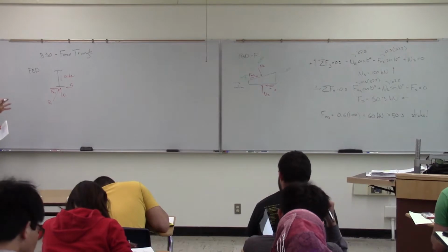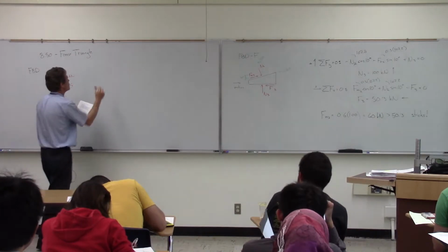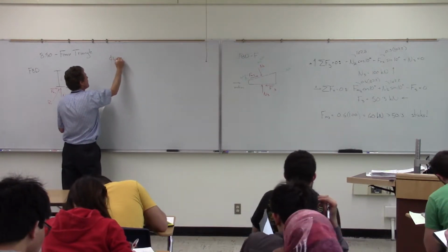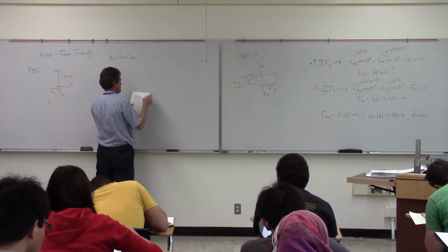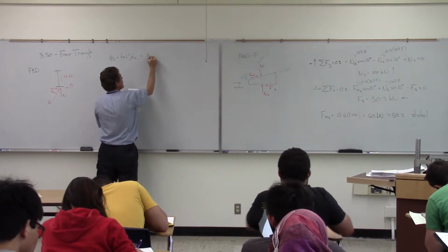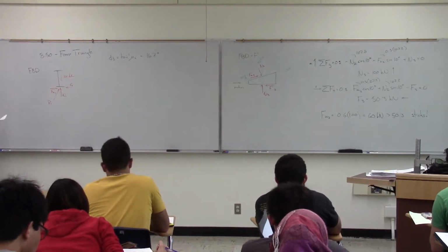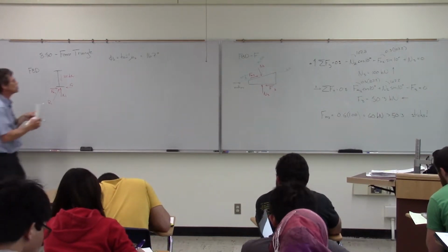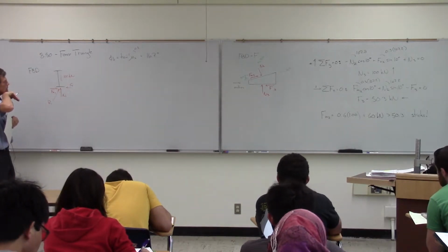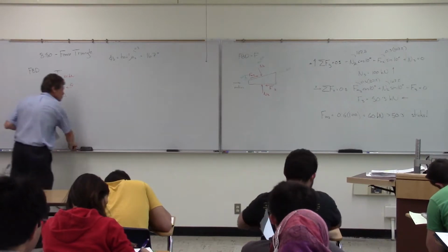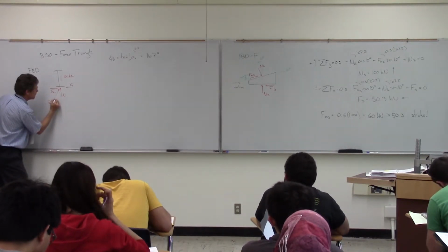Okay, so a couple of things. When we start using the force triangle, we're going to start describing our friction in terms of this friction angle. And remember the definition is that the inverse tan of the mu of S, which was 0.3 in our steel-to-steel cases, was 16.7 degrees, which describes this angle here.